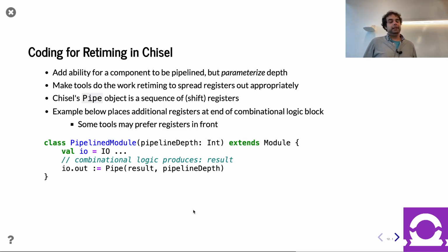That's the current methodology. It's doable in Chisel. Doing that in Verilog would be painful, but it's also doable. I often ask other researchers or other practitioners in the industry how they're handling this. And people have told me they use all sorts of pragmas or other tricks in Verilog to have registers they can turn on or off to hit certain frequencies in FPGAs. We can do that kind of stuff a little bit cleaner in Chisel, but it's still, in my opinion, more human intervention than is necessary.